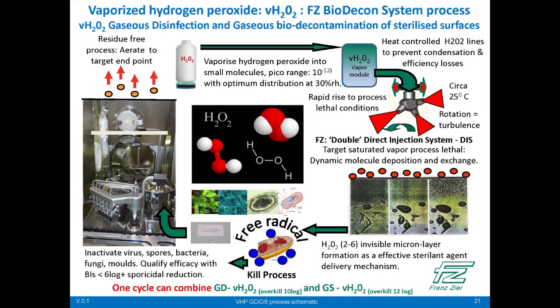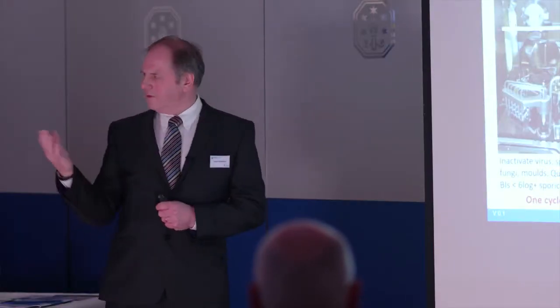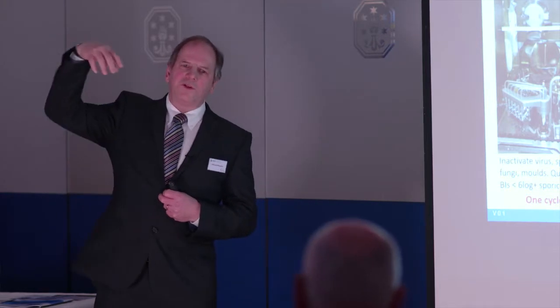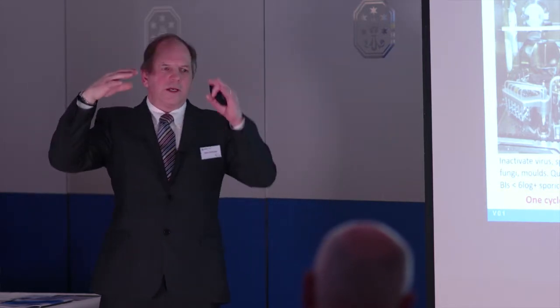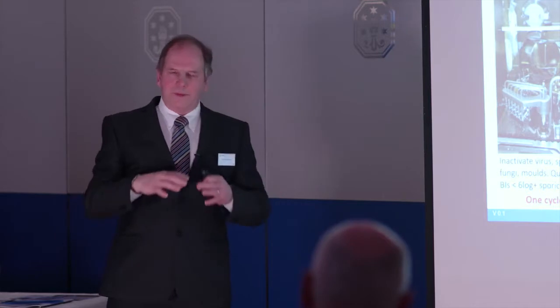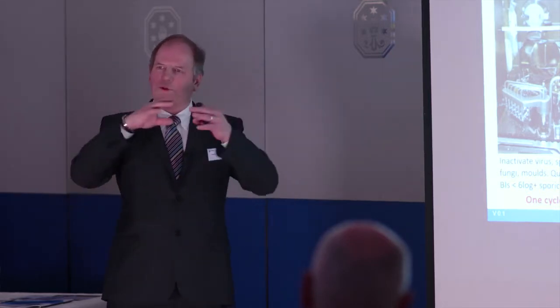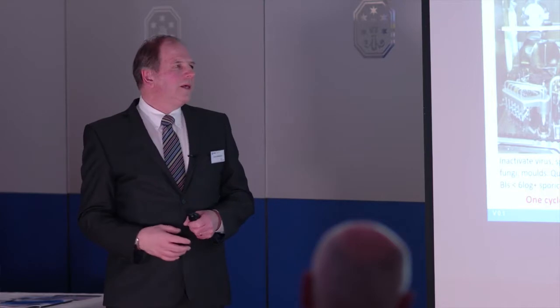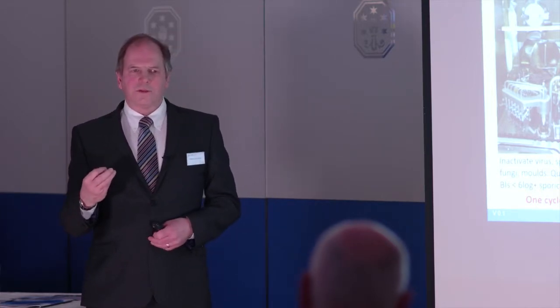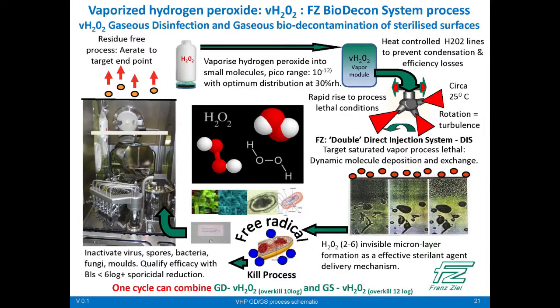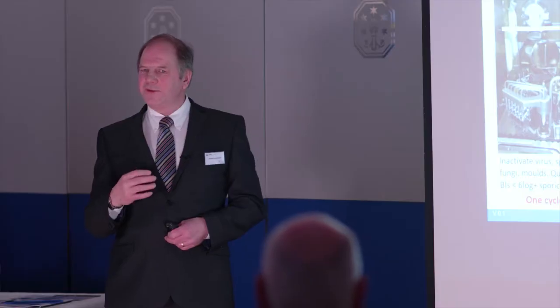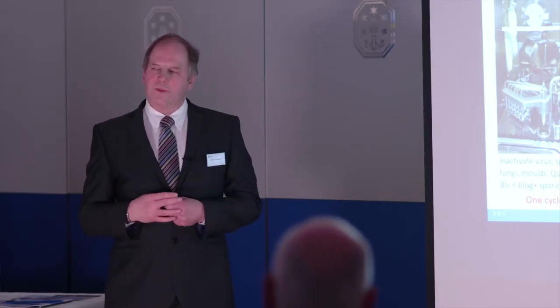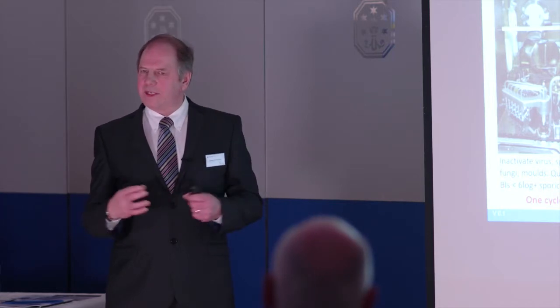They're delivered into a vapor stream, and primarily what we found is that it's very inefficient. I think Martin alluded to it earlier. If you inject above a HEPA filter and try to get the peroxide through to build process lethal conditions in the target area, that's restrictive. If you can go direct injection, then you can build process lethal conditions rapidly without the restriction. Now we need, in the pharmaceutical industry, to take all risk out of where the containment boundaries are and where the contamination aseptic boundaries are.